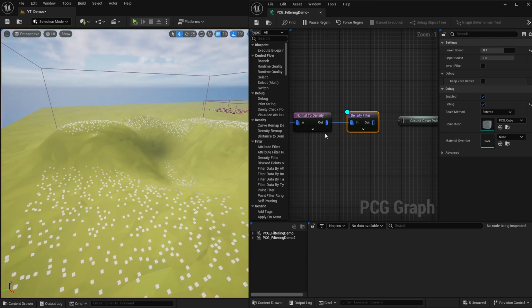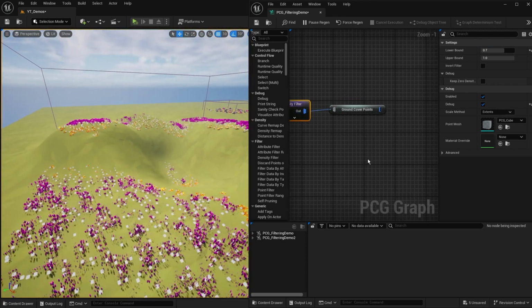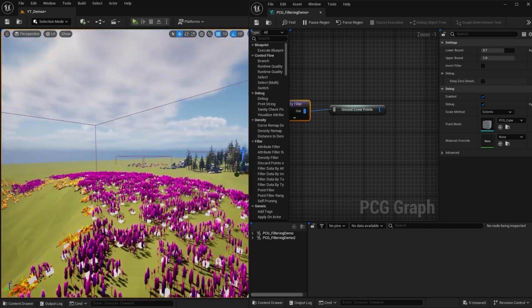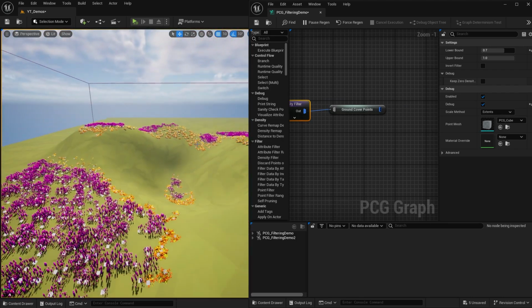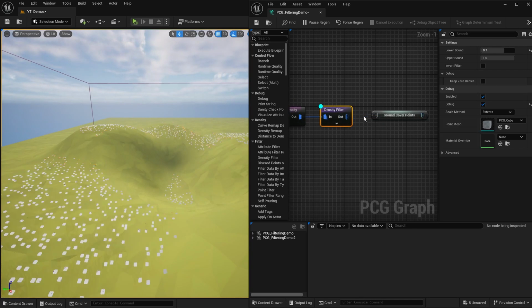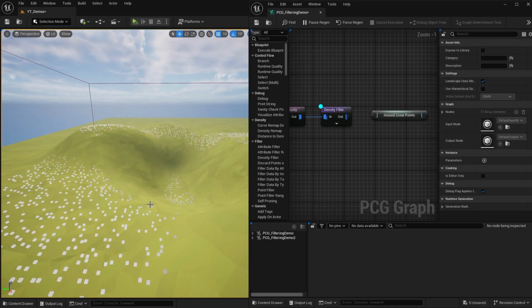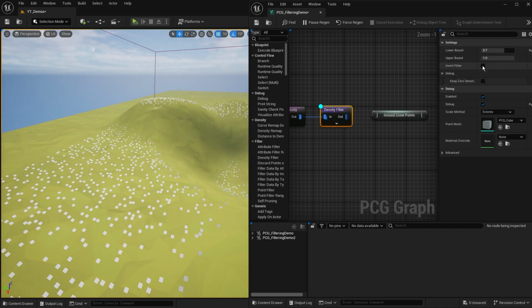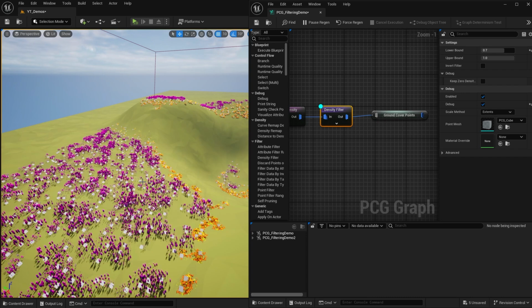and now I've only really got the ground cover happening on the top flat areas. Okay, so let's try and put that in there. Well, it's better. We don't have all the stuff on the side, but now we've only got purple flowers all the way around. And that's because, again, if we go back and look at what the actual noise density thing is here, all of them are very much white. And if we think about it, 0.7 to 1, 0.9 to 1 of that is the purple flowers, which means 0.7 to 0.9 is that kind of ground cover bit around the outside. And that's why we get this little ring here of 0.7 to 0.9 areas.